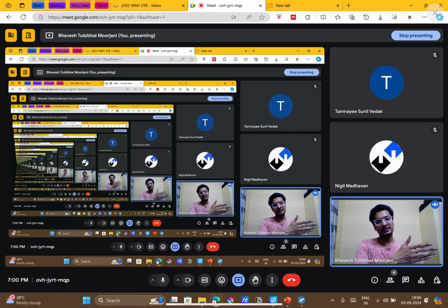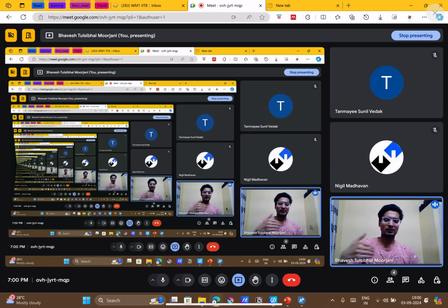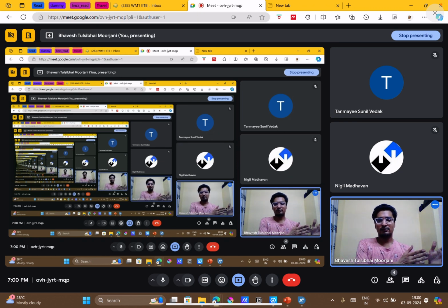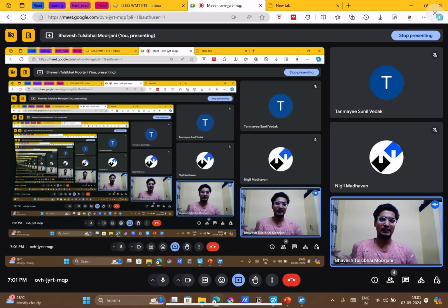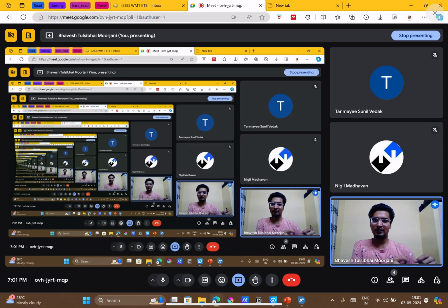In that case my design will also be different. If I just take the parameters available from Peng-Robinson without checking or doing regression, the actual equipment design will deviate from the real condition, so it's not useful. To achieve a design which matches our experimental requirements, we tune the parameters so that the calculations from our simulations are more accurate. That's the sole purpose. Did you get my point?